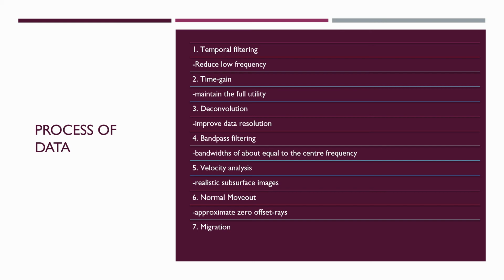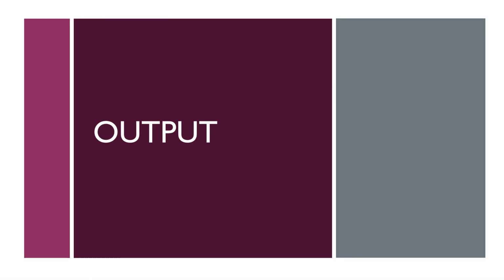The last step is migration, where this step is performed based on velocity spectrum in order to put back the reflections to their respective correct spatial position. One of the examples of software used nowadays to post-process GPR data is GPRsoft. Next, output.